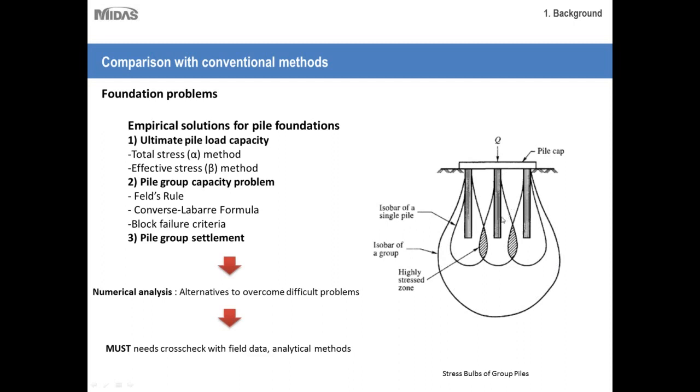But another thing that needs to be taken into account is how the isobars for the individual piles tend to merge at certain points, creating highly stressed zones. So this is something that needs to be taken into account, and we'll be going into greater detail about pile foundation analysis in our next session. But these are just things to look out for, and I'm sure you're all familiar with it when you're doing group pile foundation design.